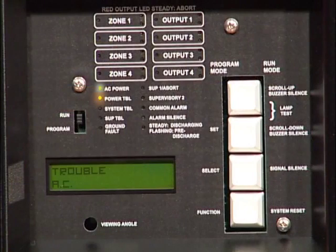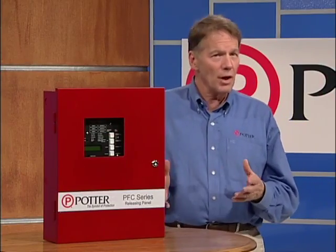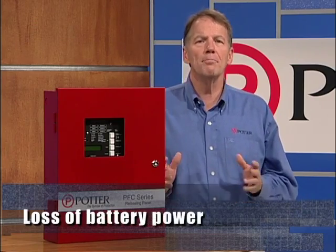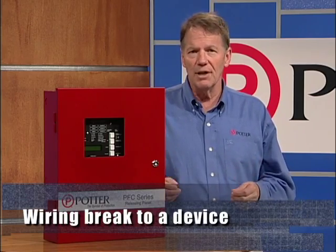A trouble signal on the releasing panel means there's a problem with the control panel or with the wiring that may render the system inoperable. Conditions that could initiate a trouble signal include loss of AC power, loss of battery power, or a break in the supervised wiring to the device.